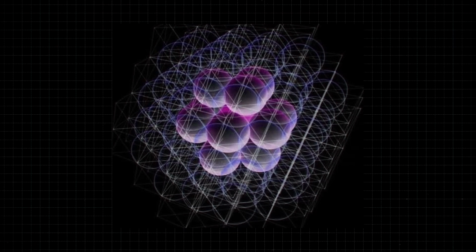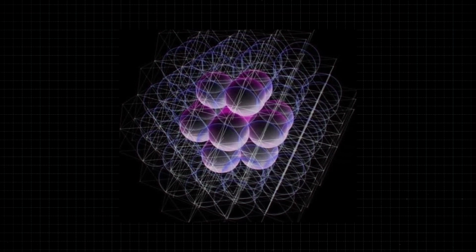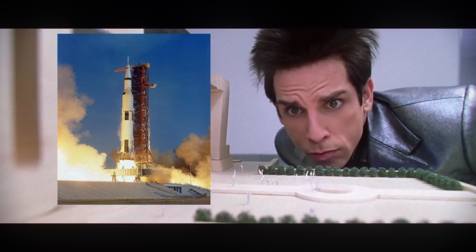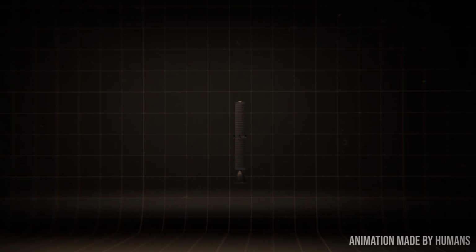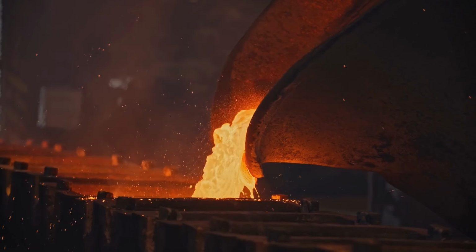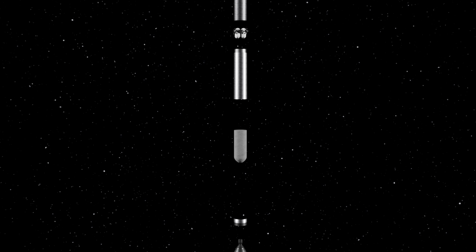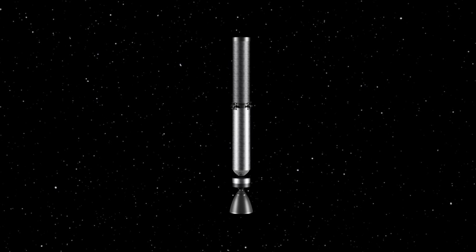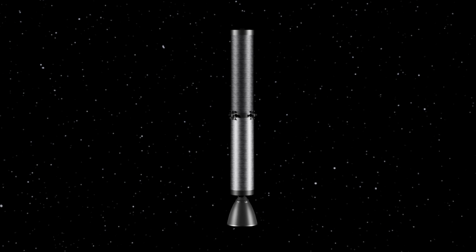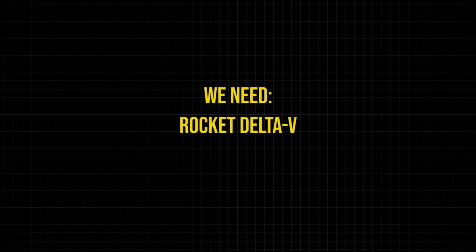And we can get an intuition by trying to imagine how one would build a sand grain-sized rocket. So we can see there is obviously some limit to how small we can go, because every rocket pod has overhead mass that does not scale away as we butt up against material property limits. But to truly know how small we can go, we need to know the orbital requirements. This is because in order to design, and therefore size a rocket, at the very top you need to know two first-order mission characterizing numbers: the required rocket delta V and the required thrust-to-weight ratio.